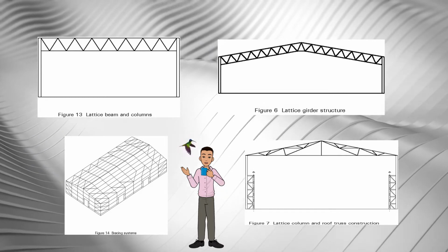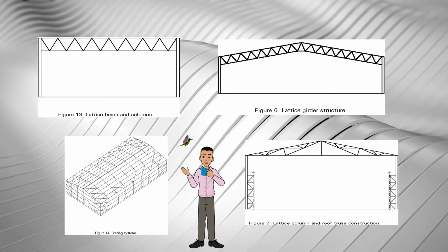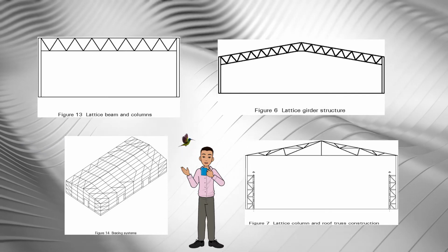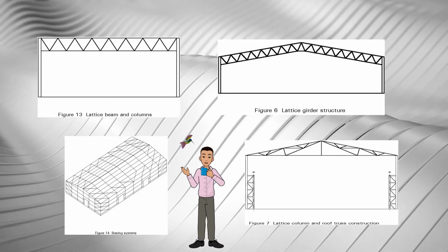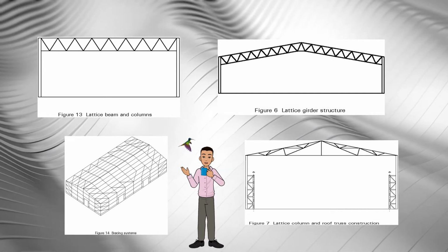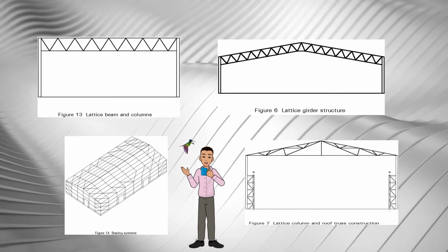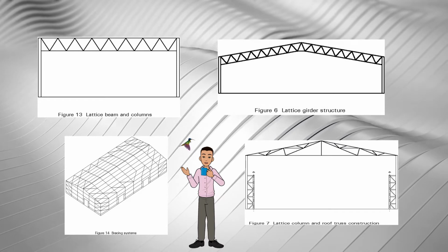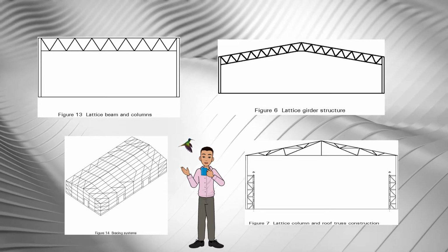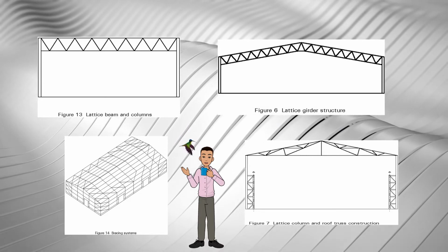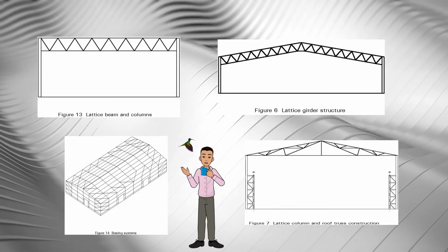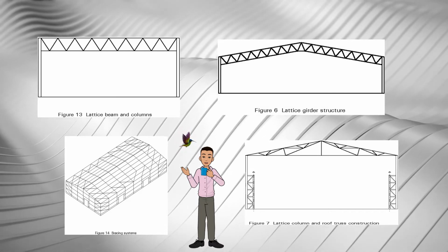To provide in-plane stability, either the column bases should be fixed or longitudinal girders should be provided in the plane of the roof as shown in Figure 14. These girders span between the gable ends, which must be braced appropriately. If the building is long or is divided by expansion joint, longitudinal bracing may not be practicable and the column must have fixed bases. Buildings using lattice girders or truss roof also need bracing to provide longitudinal stability.